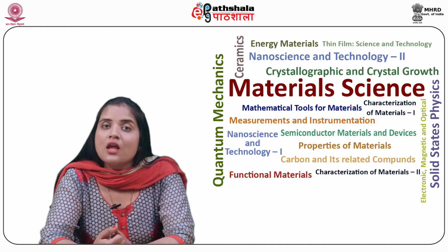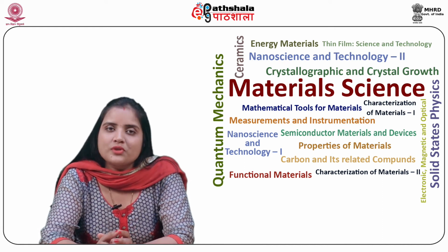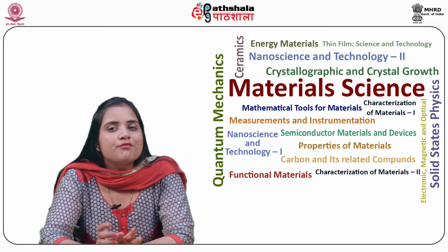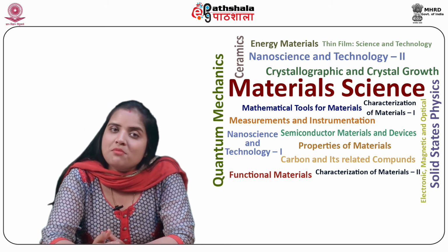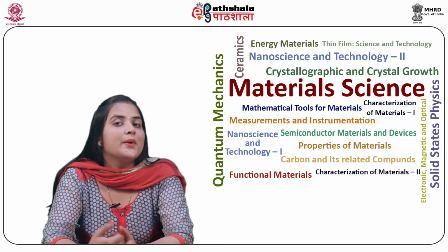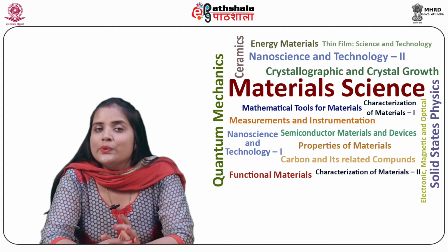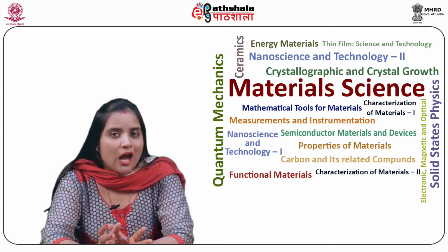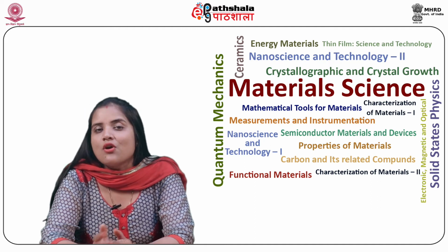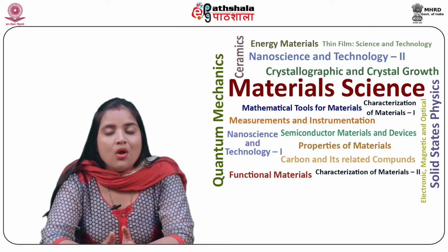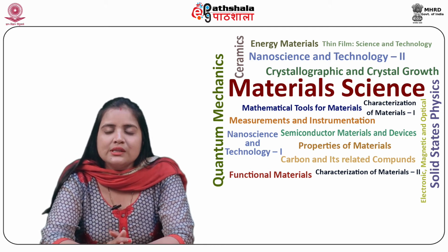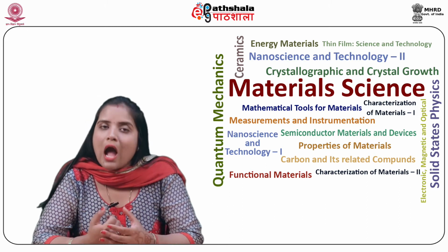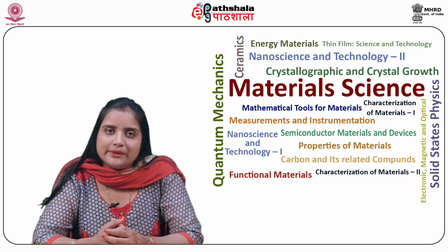Third generation cells, these include various thin film technologies and these are the future generation photovoltaics. Majority of them are at experimental stage and are not commercially available. These cells use both organic, example organometallic, as well as inorganic materials. Although at this stage they have poor absorption and low efficiencies, they are investigated for the potential of producing highly efficient and economic solar cells.